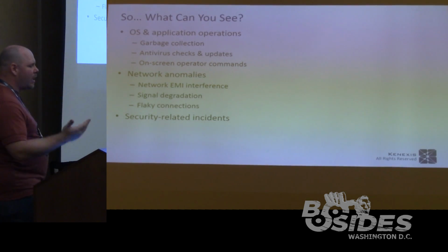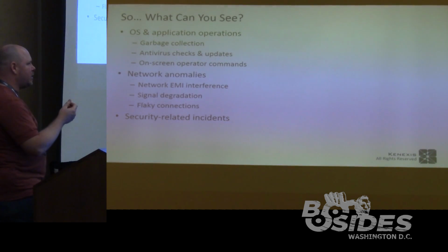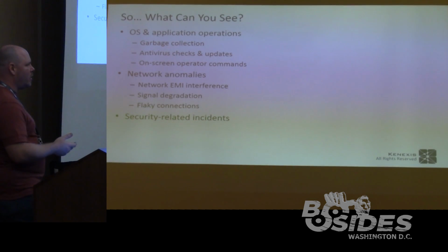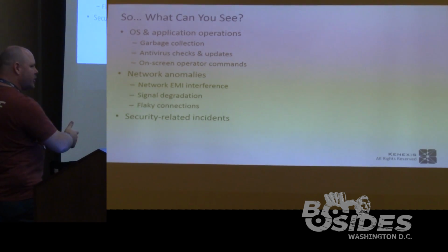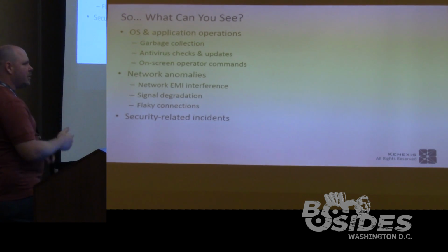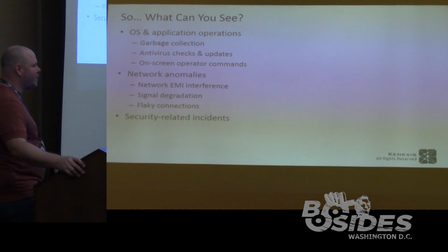I was in a corn processing plant where the corn dust was eating away at the gold contacts on the RJ45 plugs. So they had to replace their switches every 6 months to a year until they figured out, let's put in positive pressure, environmentally sealed cases and work with those. But that was only in critical locations, not every location.